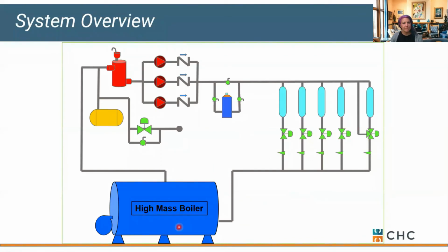So if I come back to a quick overview, guys, a standard closed-loop hydronic system, we looked at some really small components, but they have a big effect on how the system works. Remember, a fill valve, its only job is to make sure our pipe or our system is full of water. The only time I would ever look at a fill valve is if there's complaints on upper floors, assuming they're stacked vertically. If my upper floors were having some issues, first thing I would look at is my fill valve.